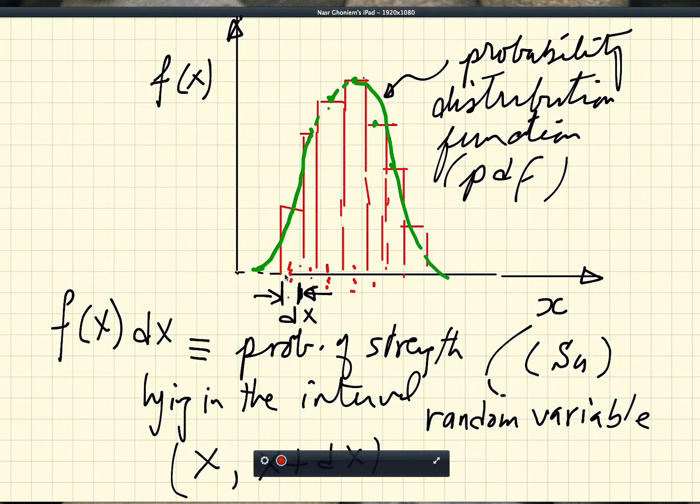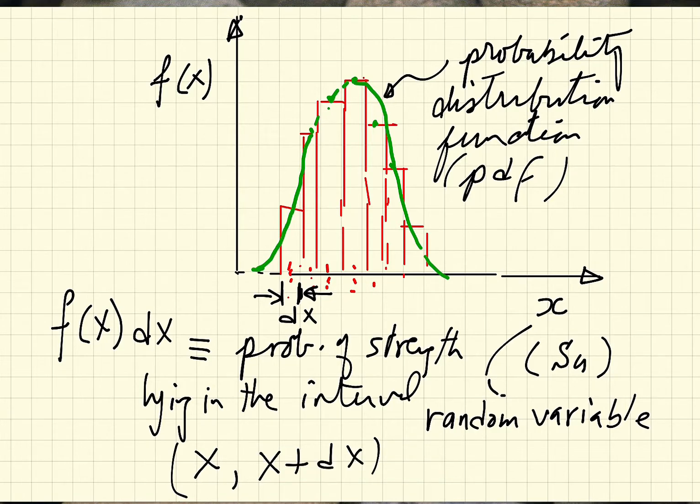And then once I generate this table, I put it in a frequency diagram, as you know from your statistics. So on this axis will be the frequency, and on this axis will be the class. So the class has a center point. So the center point will be in here. I have a center point here, center point here, center point, and so on. And then I just tally. I have 2 samples that have the strength in this range, and I have 18 samples that have strength in this range, and so on. And therefore I can build what is known as the frequency diagram that you know of from statistics.